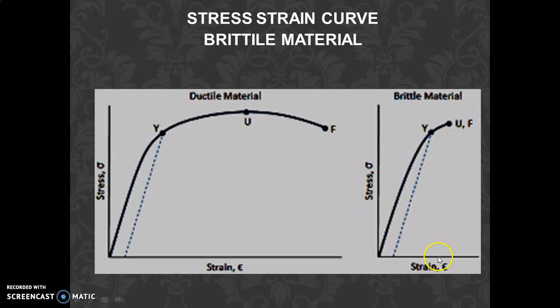So stress is directly proportional to strain up to this point, and later on a crack directly happens inside the material and failure of the material into two pieces will happen. This is the brittle material. We have taken cast iron as an example. So in case of cast iron, if you see, this kind of direct failure happens, and this is the ultimate stress. Is it okay? So that's why we consider it a brittle material, where when load is applied, breakage directly happens and a very small amount of strain is present. Thank you.